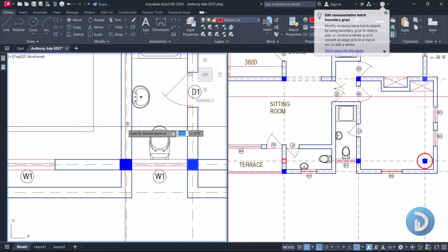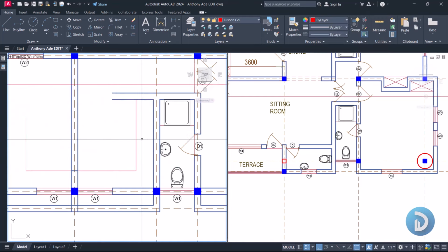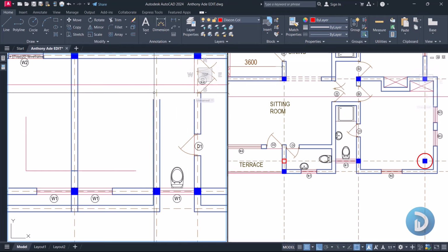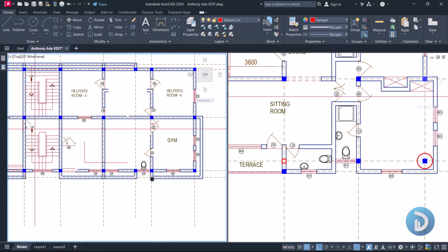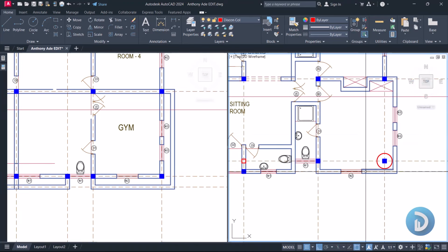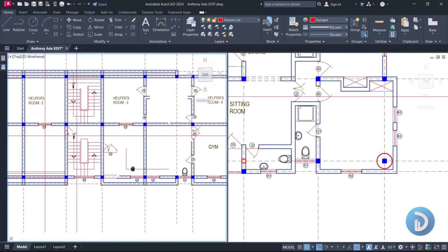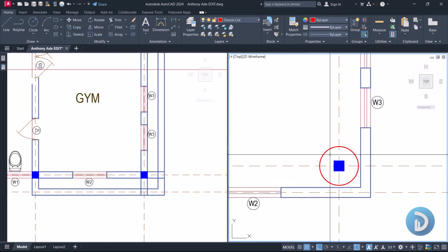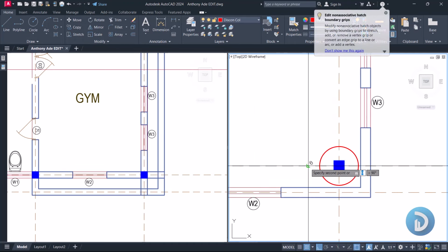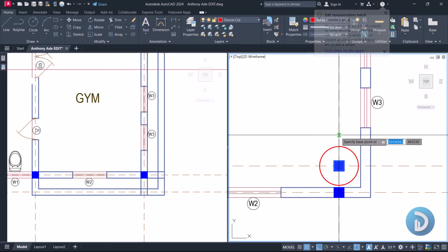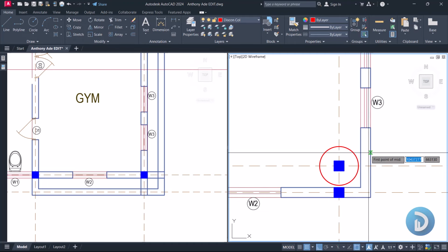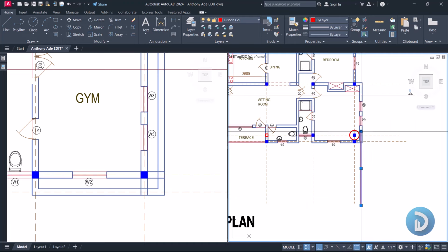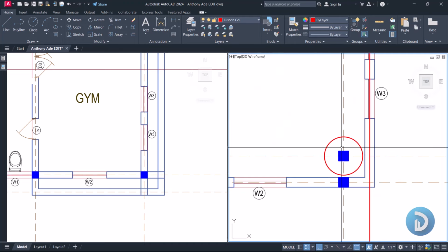We'll copy this. This is just a replicate of what we've done on this left hand side, and we'll erase all of this. Then we have our cantilever just coming out from this part. Then to solve this final issue here, we'll do the same thing we did on the left hand side, and we'll extend this here, extend this as well. Then we can choose to copy this from here to here, and also let's create a grid line, and also copy this from here to this part.